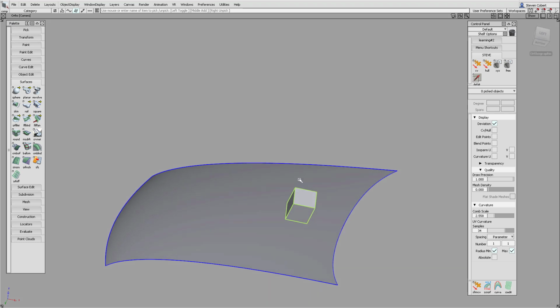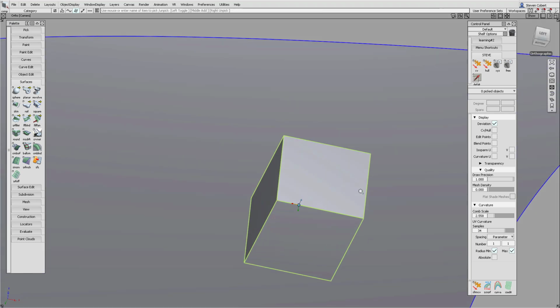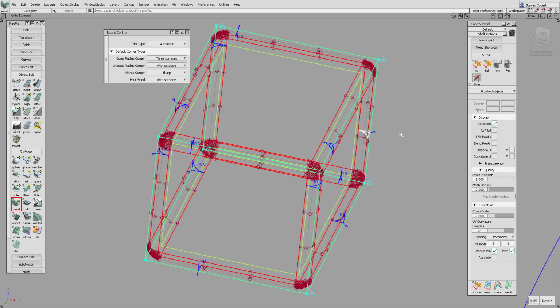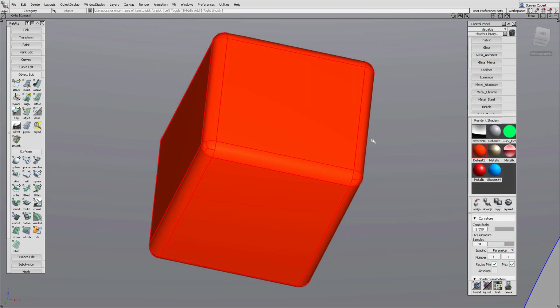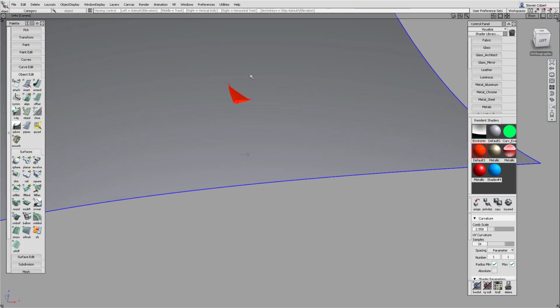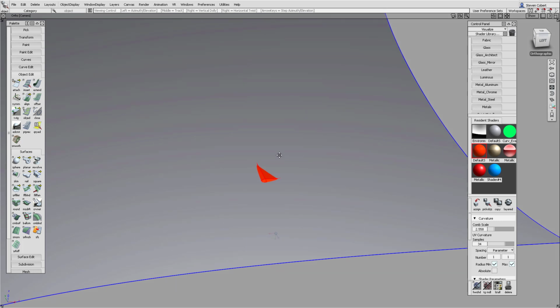In this example, we have a surface that needs to clear a packaging object by 10 mm. If we take the package model and offset all of the surfaces by this amount, and then use round with a radius of 10 mm, then we'll have a package envelope. We can use this to assess whether we have enough clearance between the surface and the package. The benefit of round for this application is that all of the edges can be done in one go, including the corners.